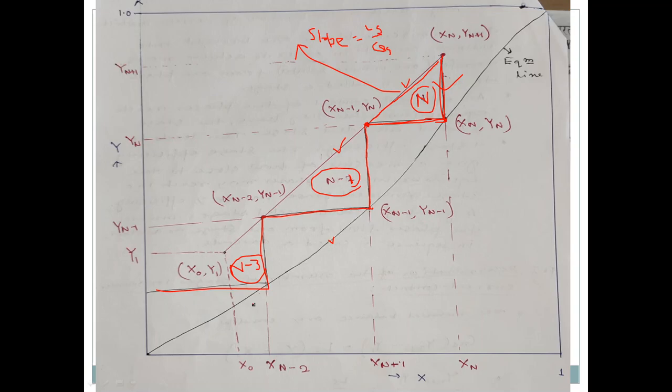So see here, I can calculate the height of the column easily, because I know the tray spacing, which is generally 1 feet to 3 feet. I will discuss later in the next chapter in detail what the exact spacing will be. It is told that it is 1 feet to 3 feet, but generally when flow rates are high, it is 3 feet, and when flow rate is low, it is 1 feet. It depends on the flow rates, and other conditions that I will discuss in the next chapter. But once you know the spacing between two trays, let's take 1 meter, and you get 3 trays, what will be the height of the column? Your height of the column will be 3 meter.